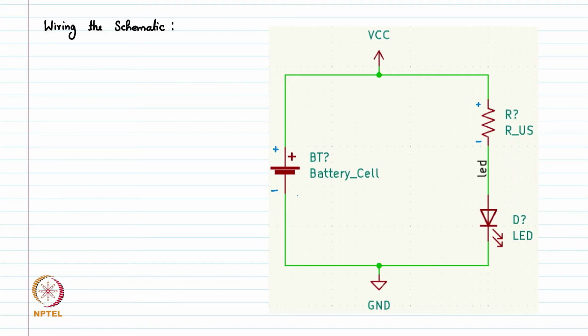So that will add a wire wherever our cursor is. We point our cursor to this point, click on this point and press W, and one wire will start coming along our cursor. So we route it like this. We go here, click on this point and then click on this point. So once we start from one terminal and end at another terminal, automatically one wire will be connected between these two terminals.